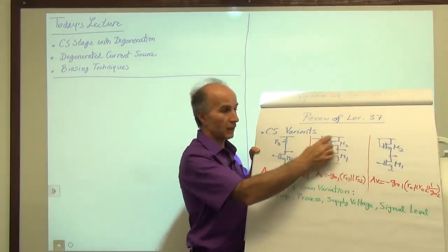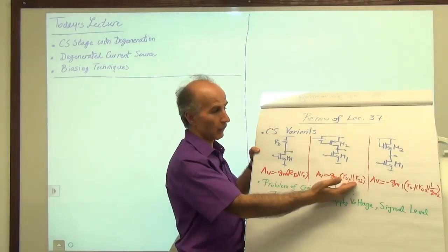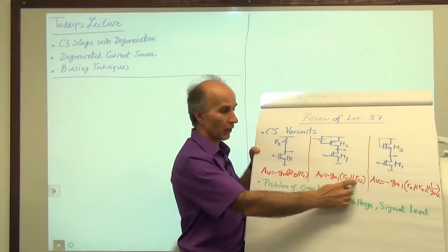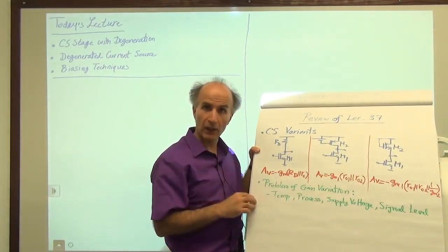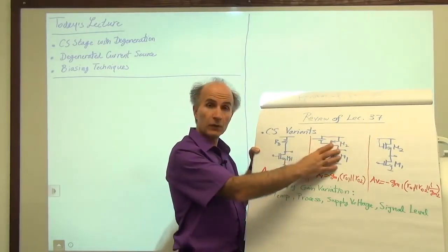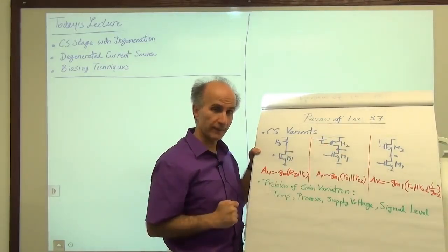So we analyzed the current source, for example, a PMOS current source, and we saw that overall the voltage gain will be like this, and our hope is that RO2 is greater than RD. And many times that is possible. Okay, this circuit is also used very often in designing these amplifying stages.